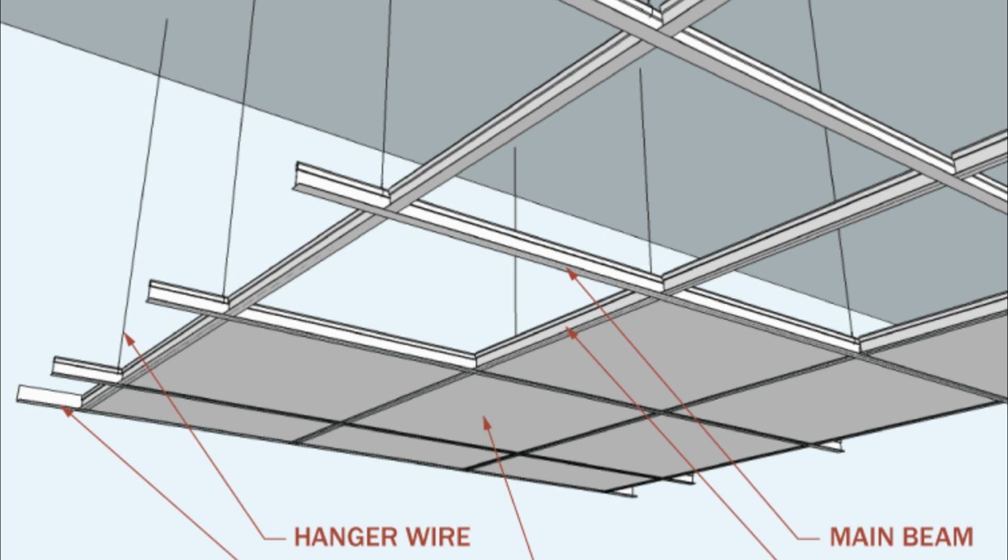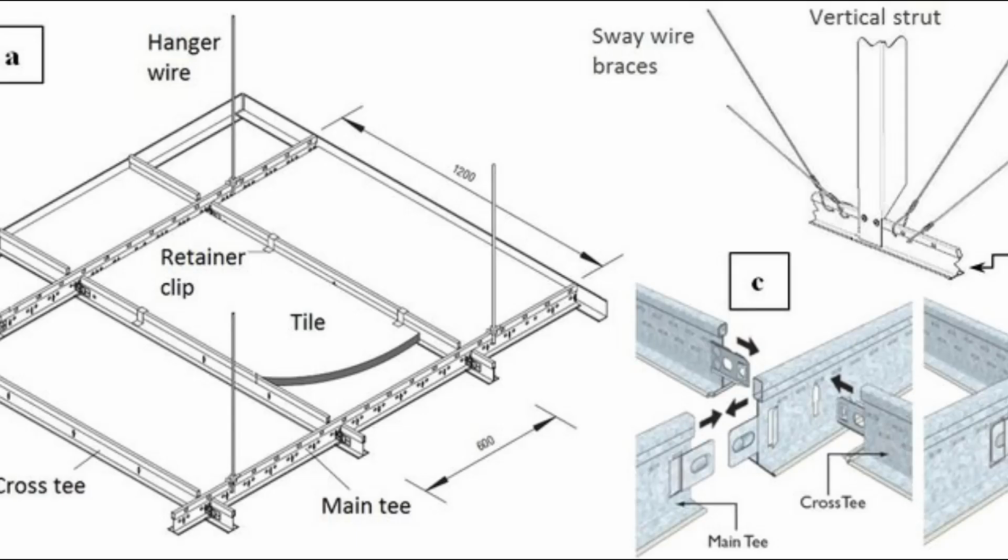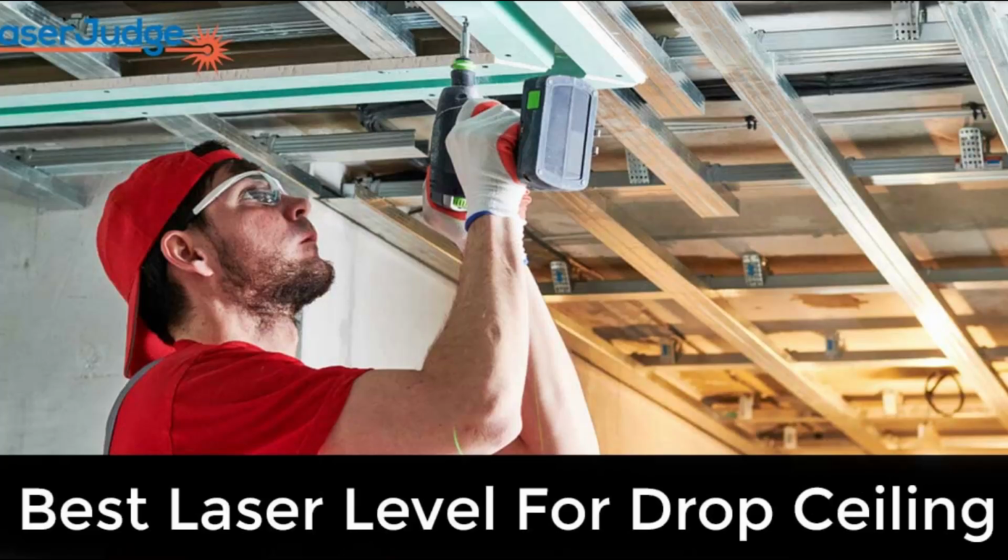In the case of an angled roof, the wires will be cut shorter if the roof is flat, but if the roof is angled, the wires will be cut accordingly. Use chalk lines to mark straight grid lines from the center to the walls. Then find a dead square, a perfect 90-degree corner from the center to the wall, either slope or flat ceiling. Ensure your grid is straight and aligned. Plan for lighting and HVAC placement.